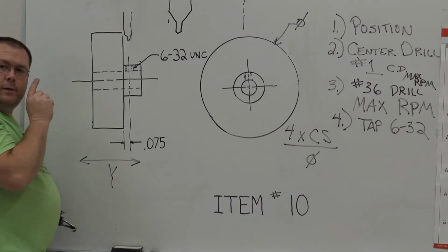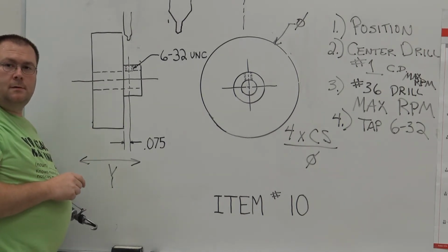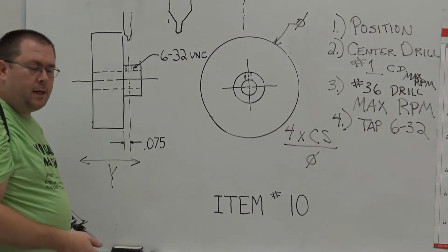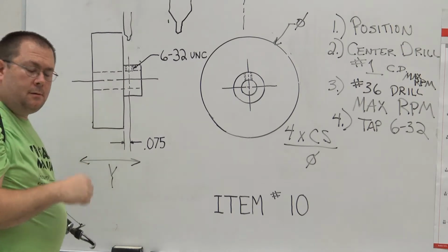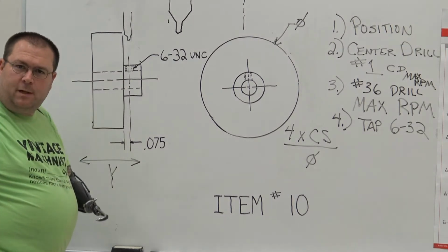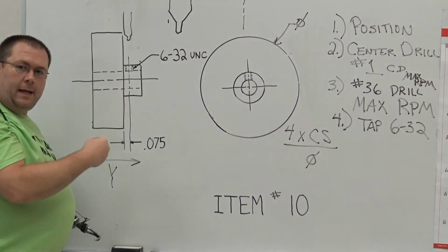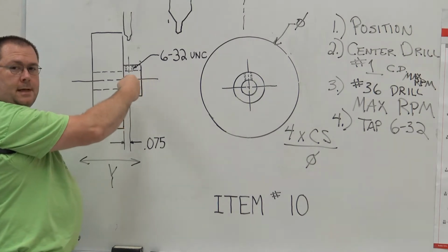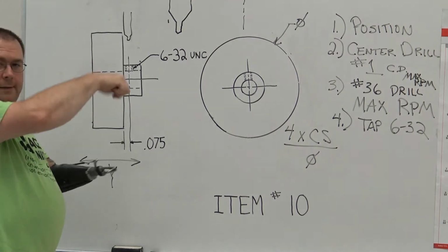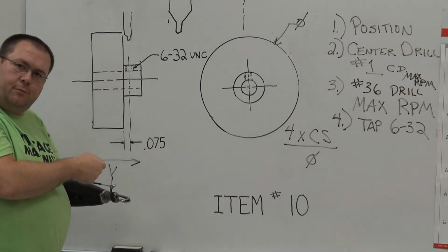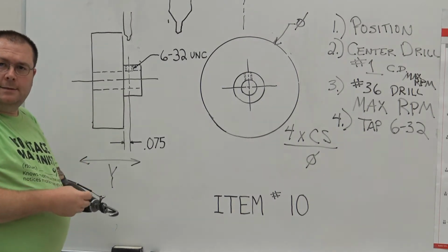Before we threaded, what did we say cutting operations generate? They generate burrs. So we got a couple different mechanisms here that we can use. Through the center hole, that hole was dimensioned at .1885 plus .0001 minus nothing, right? That way it's clearance. We can get that .1885 reamer, spin it down inside the hole. We can do that after we take the part out of the machine because we're done holding that tolerance. Take the reamer down through, you can spin it by hand. Now a 3/16 pin will go down inside the hole.